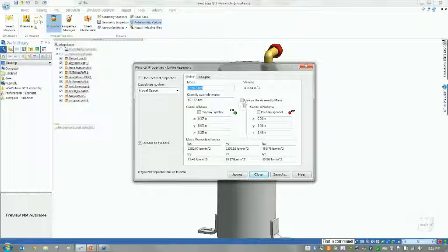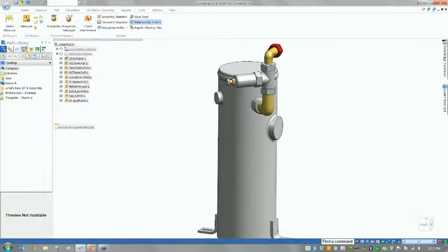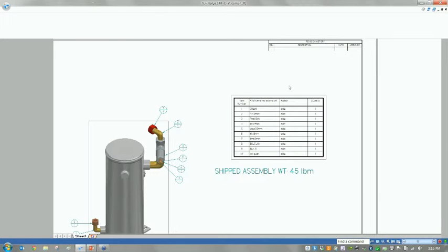So in ST8, we get the option now to use as the assembly mass. So here's the mass when we overrode the quantity. If ever you're in doubt, just read the sentence backwards. Here's the mass when we overrode the quantity. It's now 45 pounds. Do you want to use that as the overall mass? If I say yes, and I say update, then that 45 right there, we'll save this again. Move a few things here. We'll save this again, and I'll close this out.